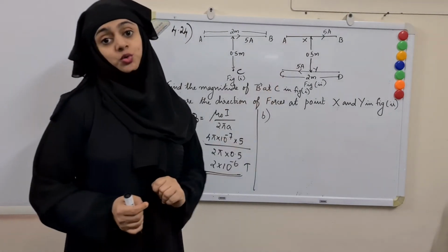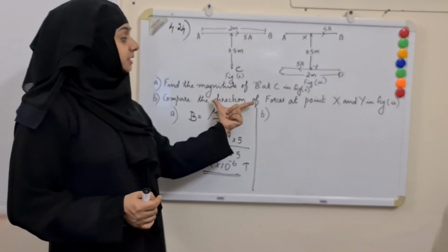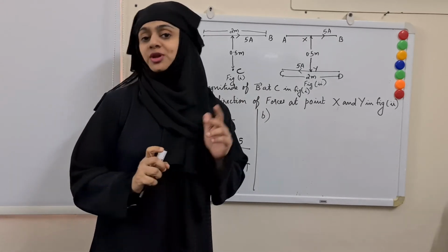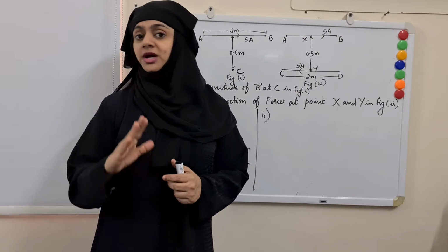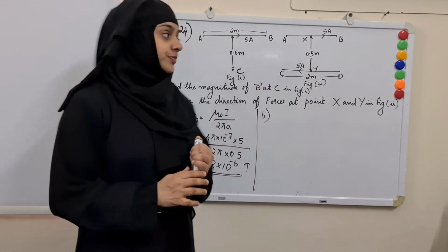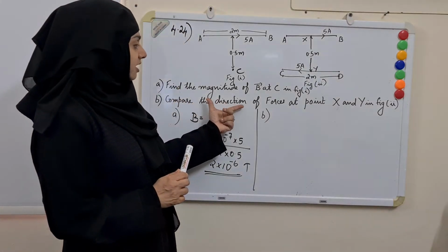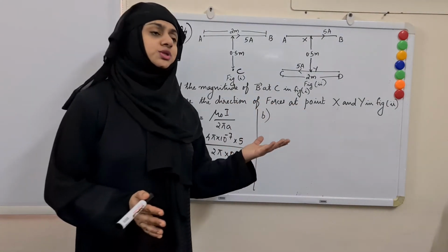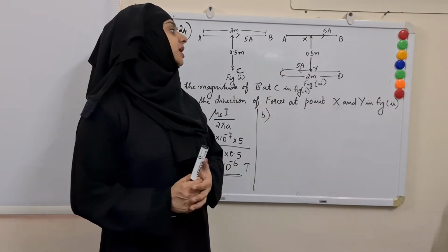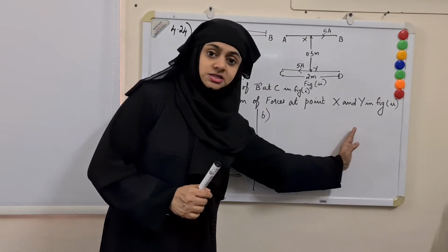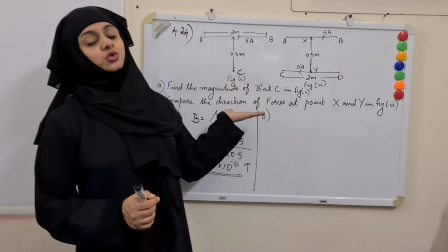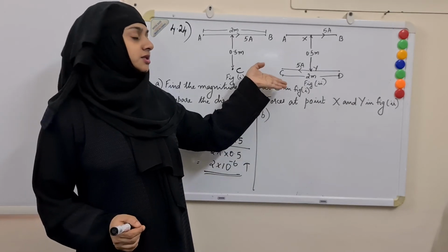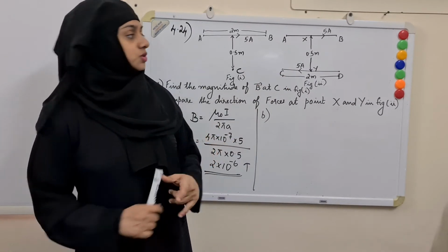So this is figure 2. We have to compare the direction of forces. So we have to use the right hand rule and Fleming's left hand rule in order to find the required directions. Even though in the question they have asked just the direction of forces, it will be enough if you use these two laws and find the direction and mention that in words. Sometimes they may ask you to find the magnitude as well. So here we will find the direction and also magnitude.